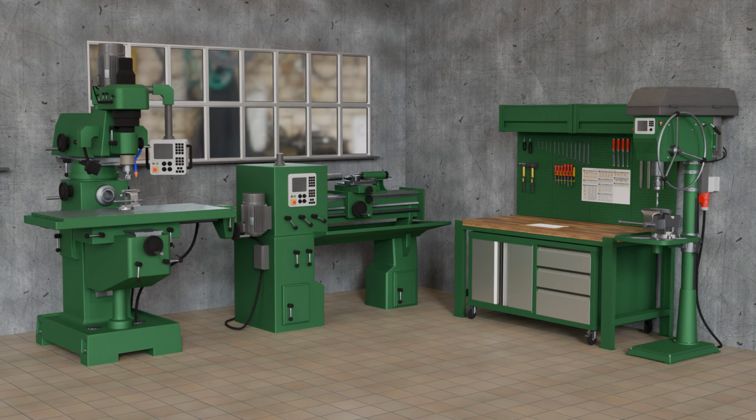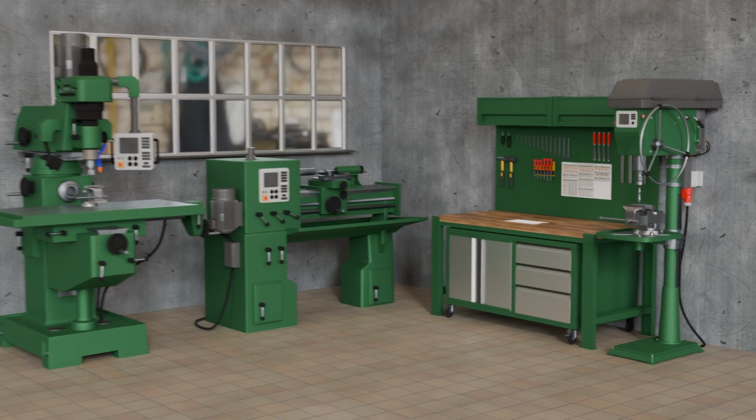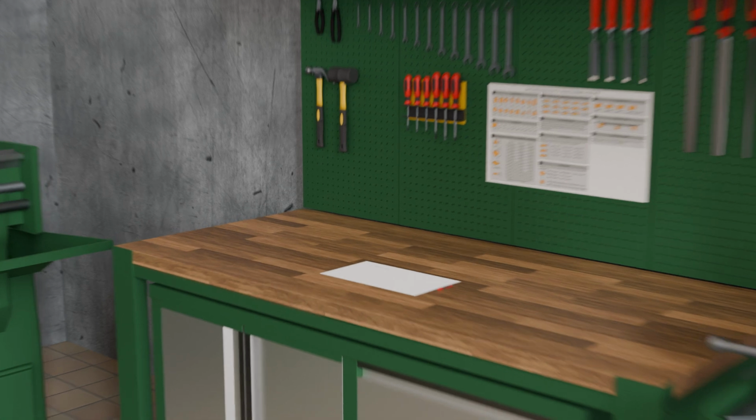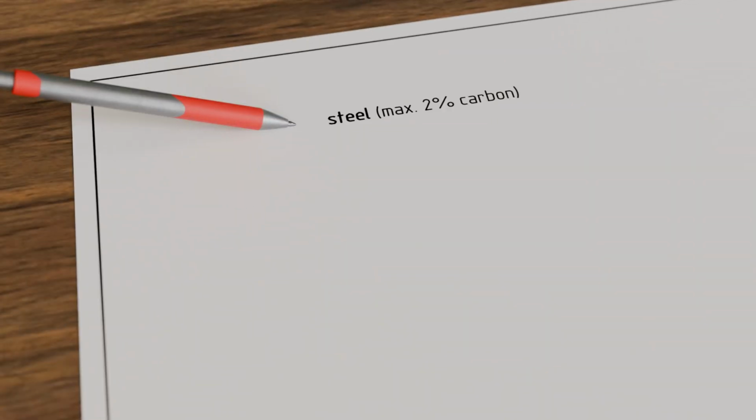In this video, we take a closer look at the classification of steels, the various steel types, and their uses. Steels can be classified according to various criteria, with a carbon content generally below about 2%, except for certain high chromium alloy steels. If the carbon content is higher, the material is referred to as cast iron.